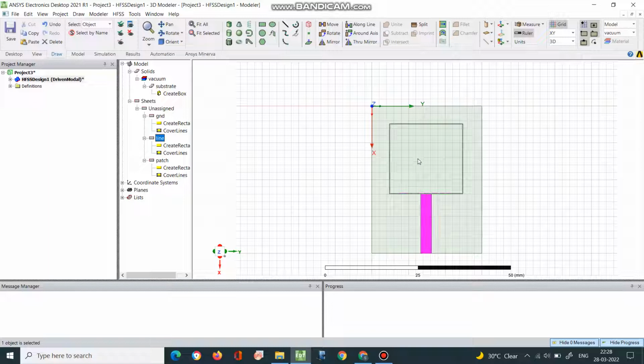So now you can see the difference here. The microstrip line and patch is connected here, but you have some disconnect between this. So this can be directly connected, and you can select microstrip line and use control key to hold the selection, right? Use control key to hold the selection. You select your microstrip patch also.